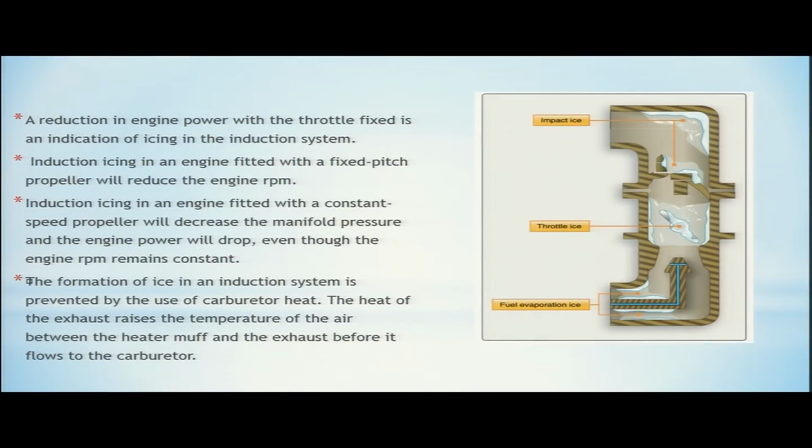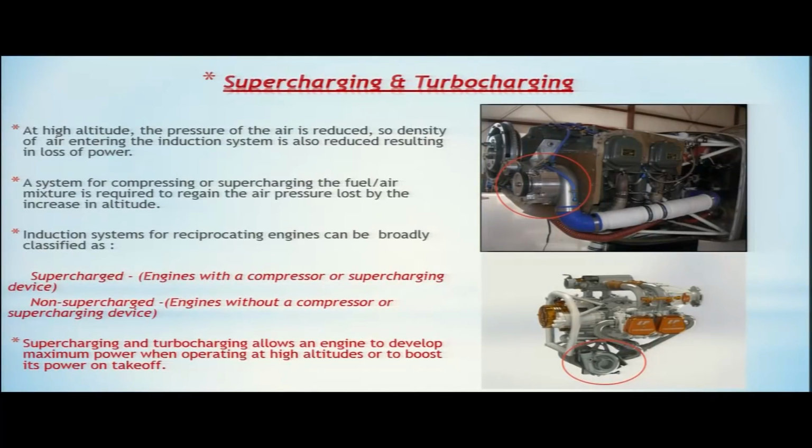The formation of ice in an induction system is prevented by use of carburetor heat. We have seen in our earlier slides that induction system icing can be prevented by use of carburetor heat. The heat of the exhaust raises the temperature of the air between the heater muff and the exhaust before it flows to the carburetor. So, we have also seen how the heater muff works and how the warm air is provided to the carburetor, which prevents induction system icing. So, this was about induction system icing.